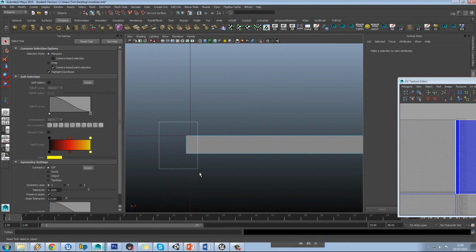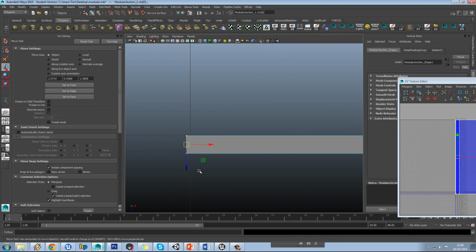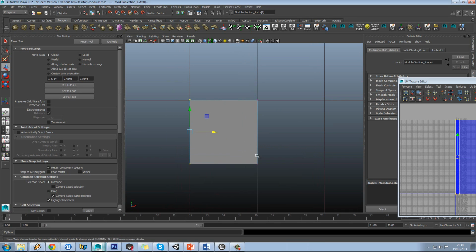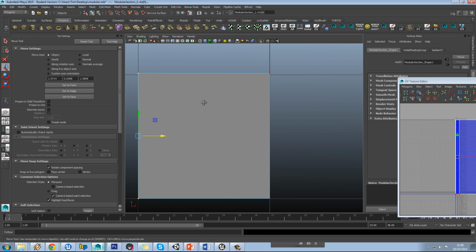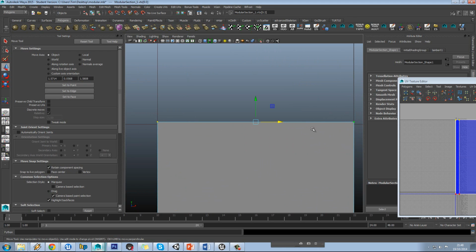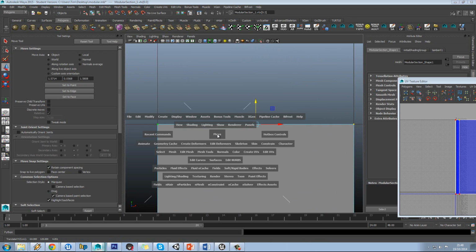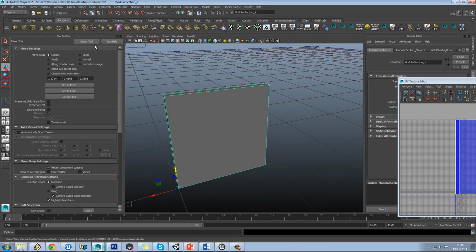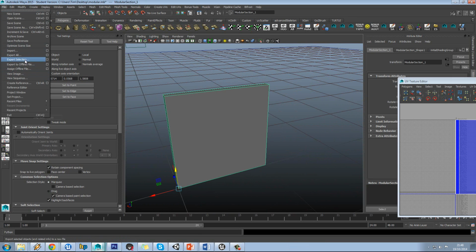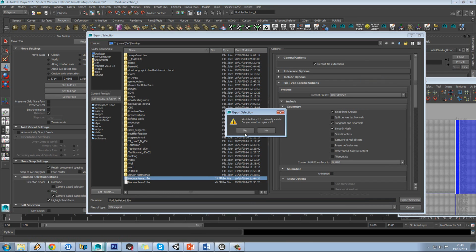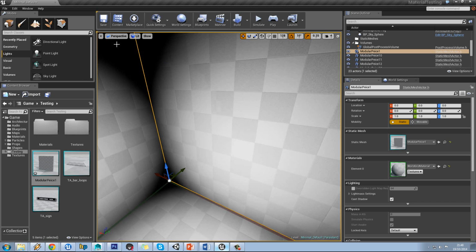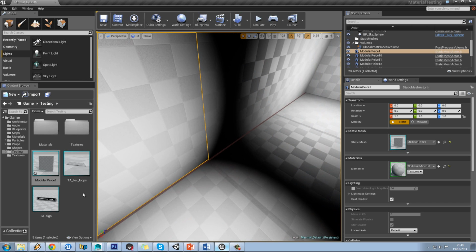So we'll just go to vertex, select these vertices, press W to go to move mode, hold X to snap to grid, just drag that on. Go to front view and make sure that that is perfectly in the square there as well. And as we can see at the top that isn't. So again, hold X and just snap down. So now that's perfectly fitting into the 128 grid space, so we shouldn't have that obvious kind of flicker going on with the overlap.